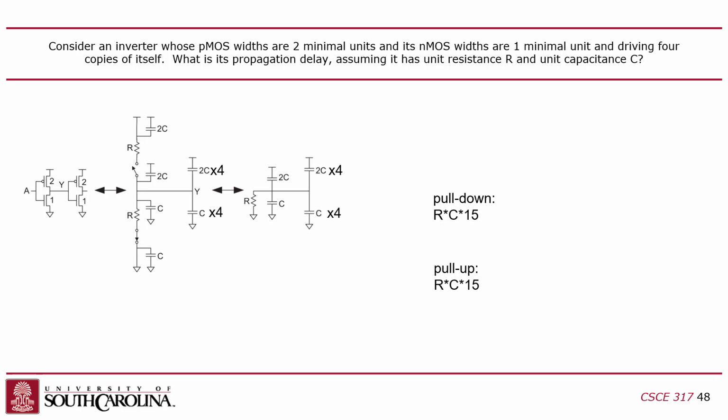So this is a very common way to characterize a CMOS technology, FO4 delay. If you have a minimal size inverter driving 4 copies of itself, what's the delay for that, right? But how would you calculate it with this model? Well, basically, it's the same thing we just did, except you're multiplying the gate load by 4, right? So it's very simple.